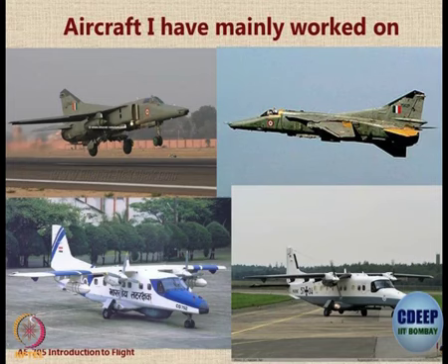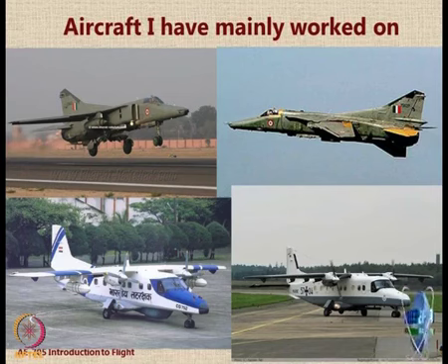Which one is this? How can you say MiG-27? One minute. Because of the shape. How about MiG-23? No, I think it is very difficult for someone to identify between MiG-21 and 23. The radome is very similar for both. I'll tell you where the difference is. The difference is in the intake.